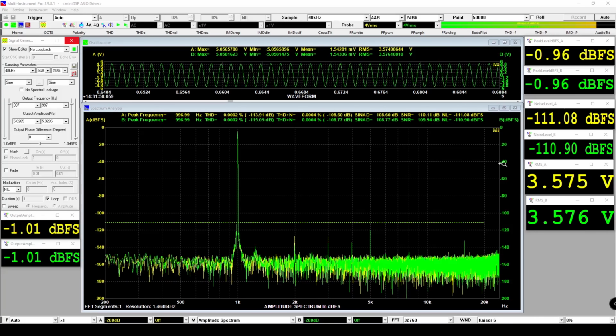And even if you cannot say the noise level from the FFT, one very useful thing is that you can see the shape of the noise floor. Okay, this is flat here, but sometimes it may get higher in the low frequencies or higher in the high frequencies. Although we won't go into details of Fourier theorem here, just to mention that I assume that you know that any periodical signal can be represented as a composition of tones.